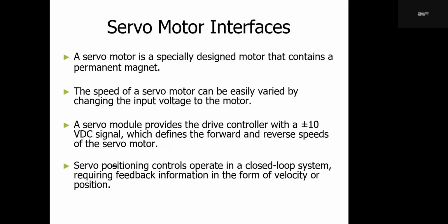A servo module provides the drive controller with a plus or minus 10 VDC signal, which defines the forward and reverse speeds of the servo motor.